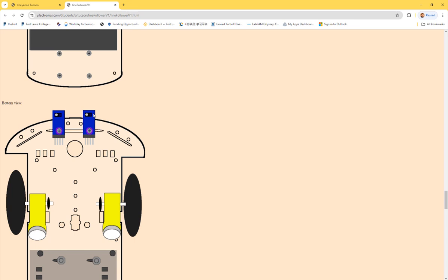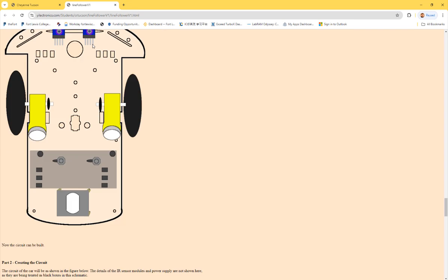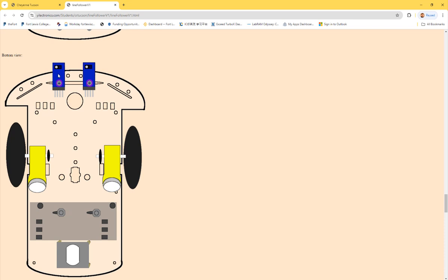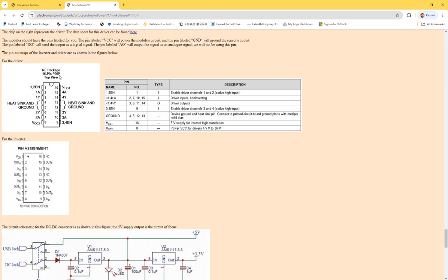So the IR sensor emits IR light to the tape. The black tape is going to absorb it without reflecting any light. So it is able to follow that track. So you can make a line tracker using a very simple analog robot. You can build it probably within like 2 sessions of 3-hour labs. Really fun project. So these are the two IR lights with a little op-amp on it, forming the little comparator circuit. I'm going to show you that today as well.